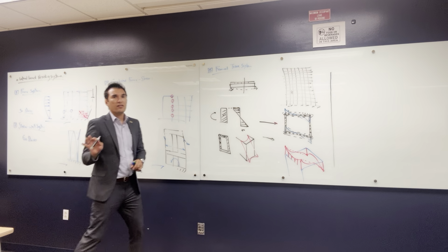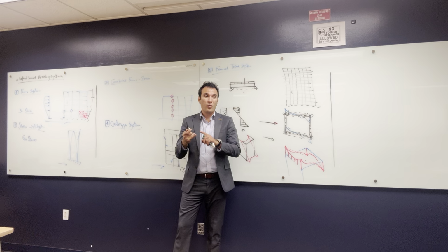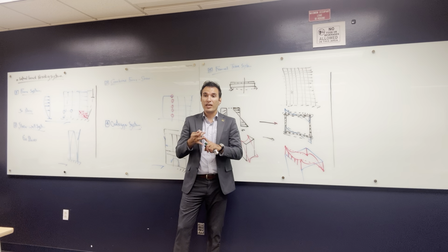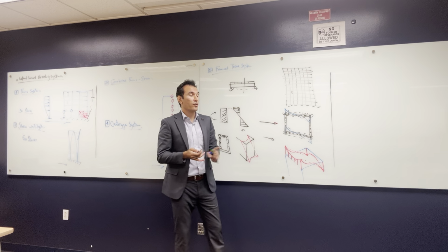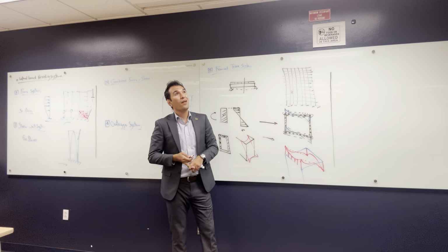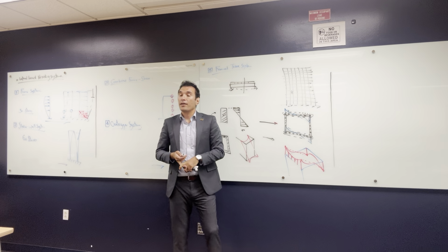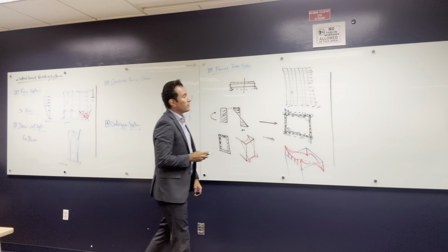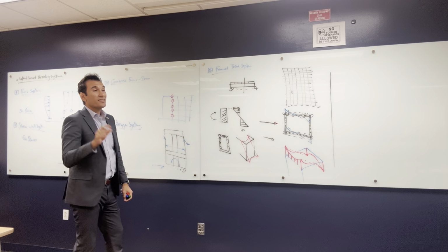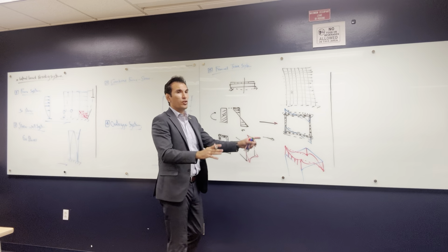And I told you there are many ways that we can decrease the shear lag. You guys remember? We can increase the column cross section. We can increase the beam dimension, the spandrel beam dimension between these two. What else? Decrease the distance between columns. So all these can help, but sometimes with all these in place, there's still huge deformation of the building.